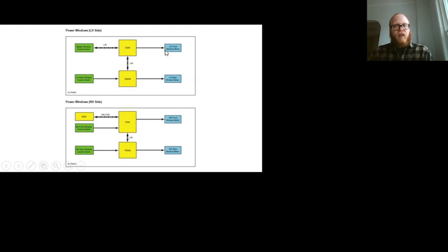Then it can either control its directly wired output. So in this case, if I wanted to roll down the driver's window, it would just control current flow through the motor in the correct direction, right? Whether it's going up or going down. Reverses polarity, so it controls that. Or if we need to control another motor, window motor in this vehicle, there's a LIN that goes to another door module that's hardwired to that motor. So these LINs are just single direction.